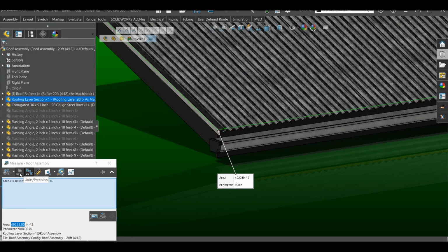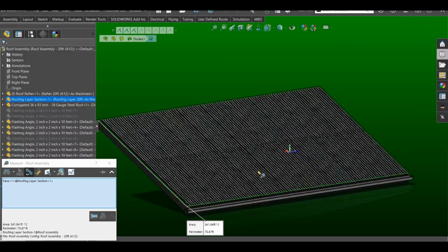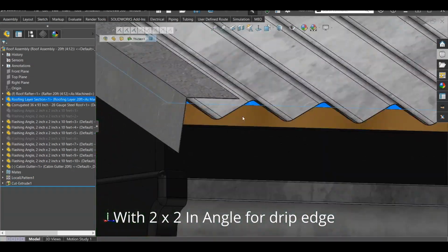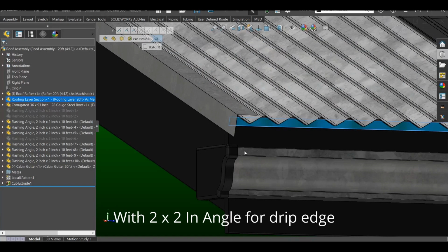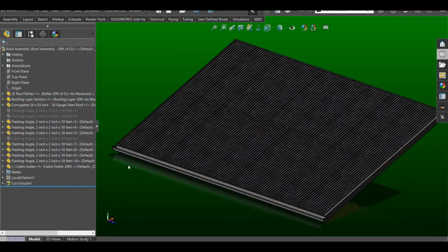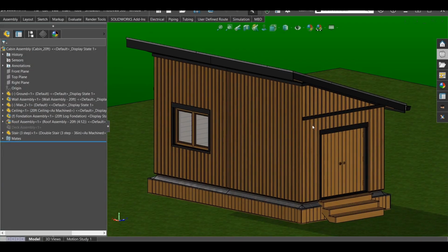So if I go here and go to feet, I can know exactly how many square feet. Okay, this is the 20. So 341 square feet of material that you're going to need. And the rest is 3/4 inch board, or you can have 3/4 inch plywood for roofing, I guess. But there is no plywood in my setup. It's all board, 100%, facade and everything.